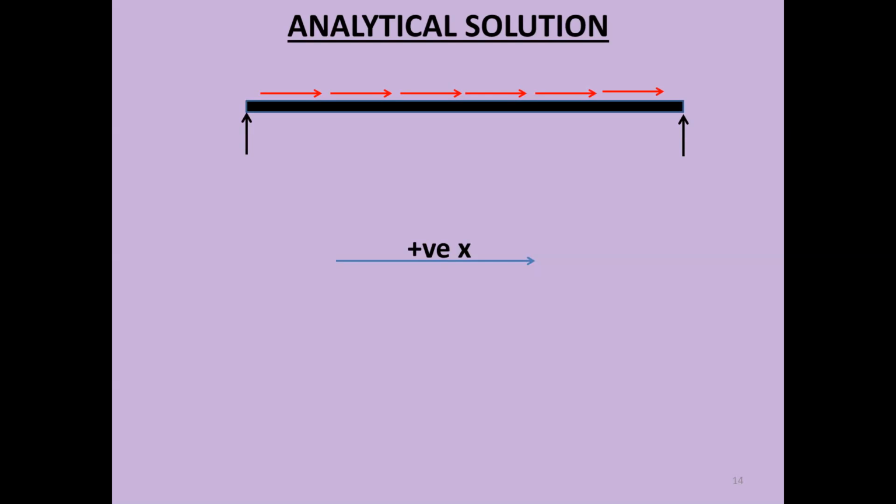Kindly remember, if the direction of the UDL was oriented towards the perpendicular direction, this element under loading would have bent in that particular case. So this would have been a beam and not a bar. But for the time being, the direction of UDL is along the length of the element. So therefore, the element is going to act as a bar and not as a beam.